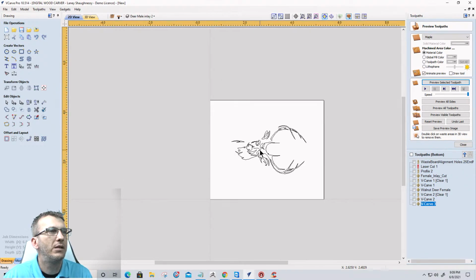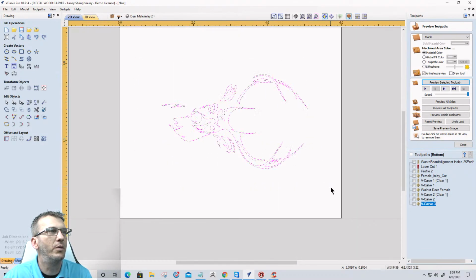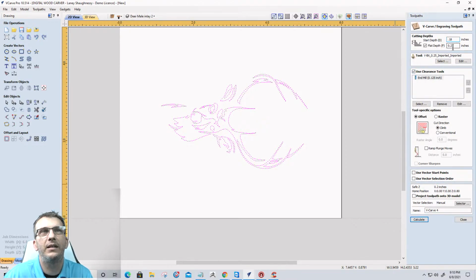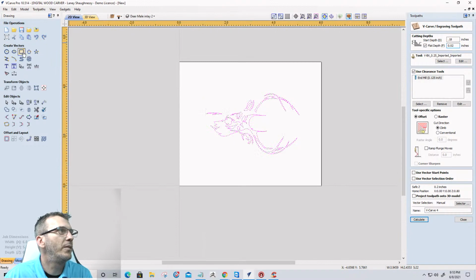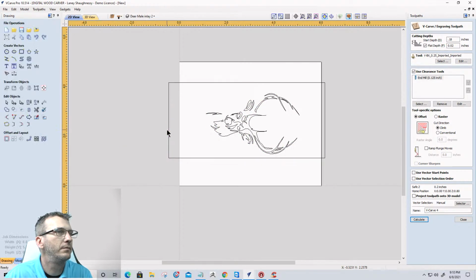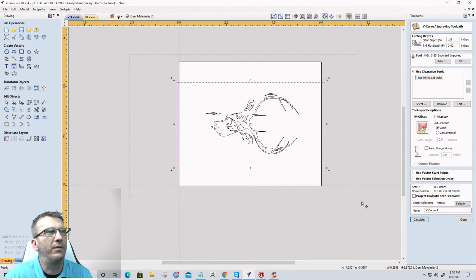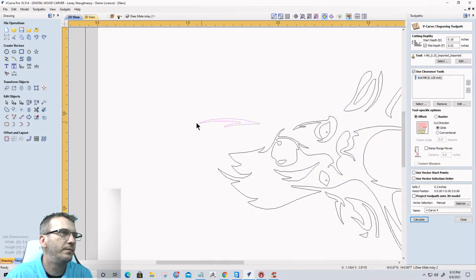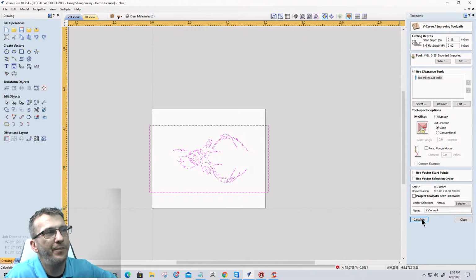Okay. So on this, we're going to create the toolpath for this one. V-carve inlay, start depth of 0.18, flat depth of 0.02. And again, oops, where's my rectangle boundary? I think I accidentally deleted it. All right, select everything there and calculate that. Oh, still got that open vector. Hold on a second. Okay, one more time. Calculate that.